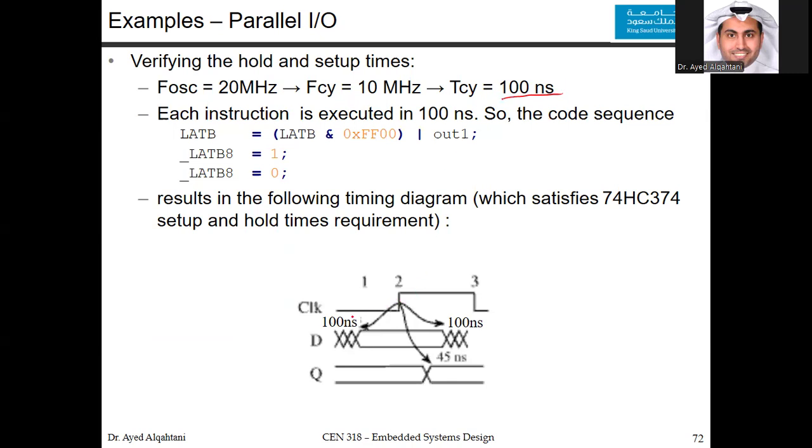So for the flip-flop to work, I need a pulse, the pulse that I just showed. So we have a setup and a hold time. Since the setup is the 100 nanoseconds that you see here, and the hold is the 1 nanosecond, you know that this is actually a rising edge flip-flop.